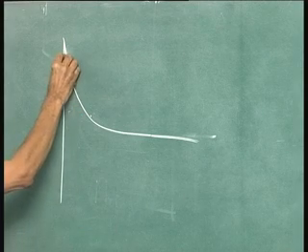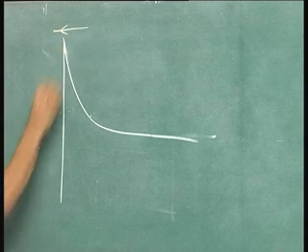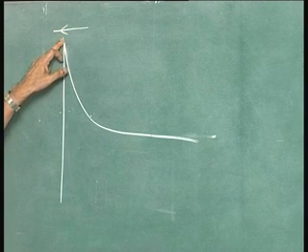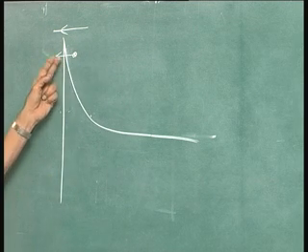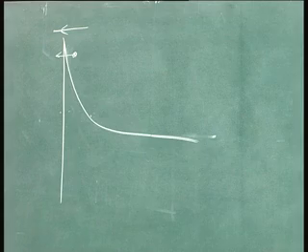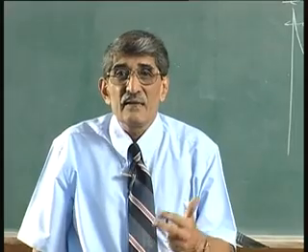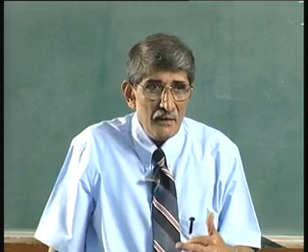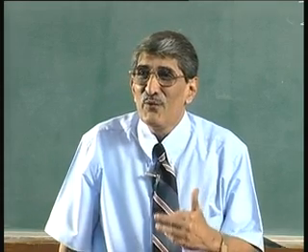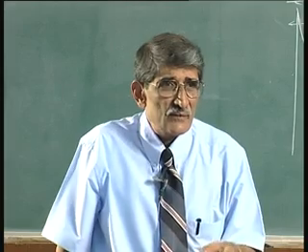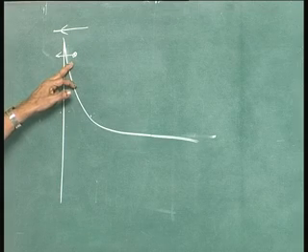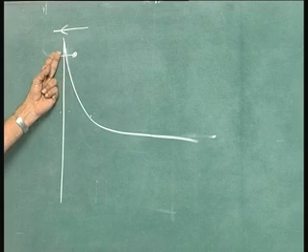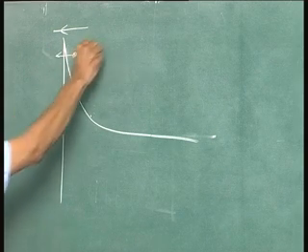But when you go to the top, what we are talking of in thermionic emission is the injection of electrons across that barrier, A. What we are talking of now is the electrons which have energy here. They find that the barrier width is very small. That is called quantum mechanical tunneling. I think the physics people frighten us by using jargon, but it is actually the fact. The Schrodinger equation solution tells you all the things. So, what I am trying to point out is you will have very easy transfer of electrons from here to here across this thin layer, that is called tunneling.